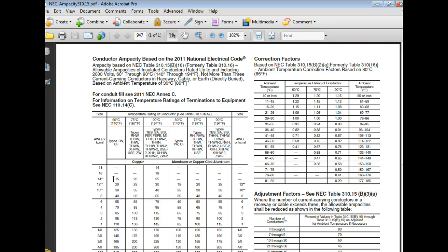It's kind of confusing because we say we want to go to a bigger gauge wire. We're talking about the size of the wire. We're not talking about the wire gauge number, right? You understand? So I say a bigger gauge wire, it means a bigger wire, but the actual wire number would be smaller. Rule of thumb is that if we wanted to run aluminum on a 15 amp circuit, instead of using a 14 gauge wire, I would use a what? A 12 gauge. So rule of thumb is to go down 1 gauge to run aluminum. Well, be careful with aluminum. What problems does aluminum have?